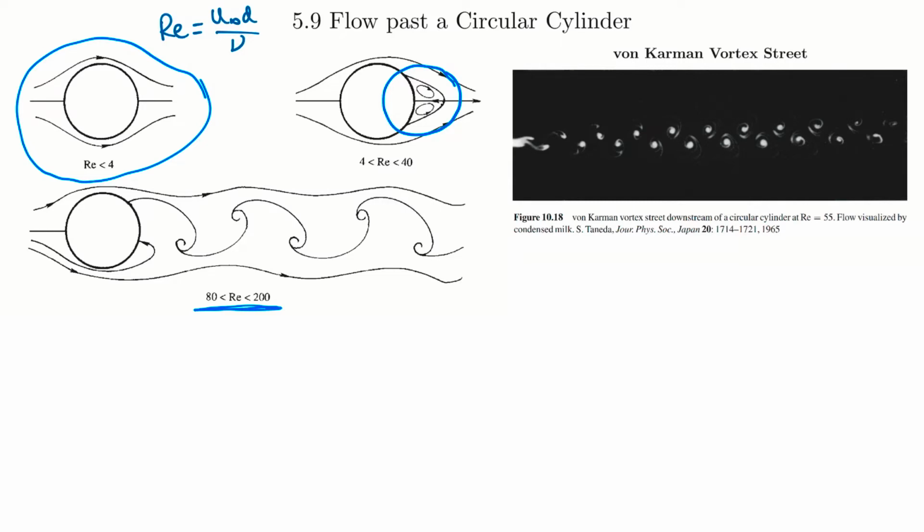The vortices move downstream at a speed that's smaller than the upstream velocity U infinity. And so that means the vortex pattern slowly follows the cylinder if it's pulled through a stationary fluid. Okay, so in the range of roughly 40 to 80 Reynolds numbers, the vortex street doesn't interact with the pair of attached vortices, but as Reynolds is increased beyond 80, the vortex street forms closer to the cylinder, and the attached eddies, whose downstream length is now roughly twice the diameter of the cylinder itself, because remember we said those will lengthen as Reynolds increases, themselves begin to oscillate. And so these attached eddies will periodically break off alternately from the two sides of the cylinder. While the eddy on one side is shed, the one on the other side forms, resulting in an unsteady flow near the cylinder.